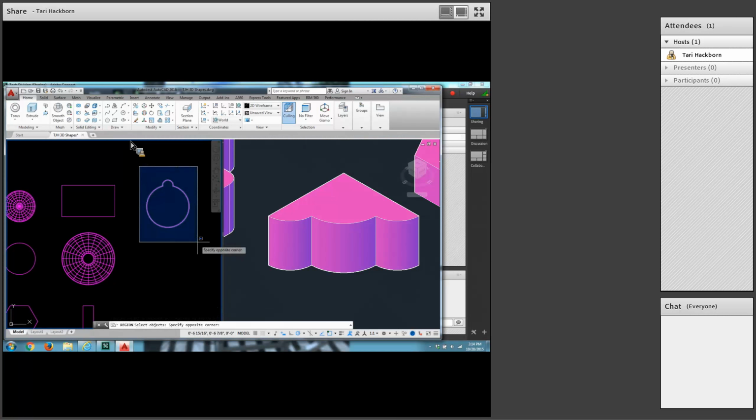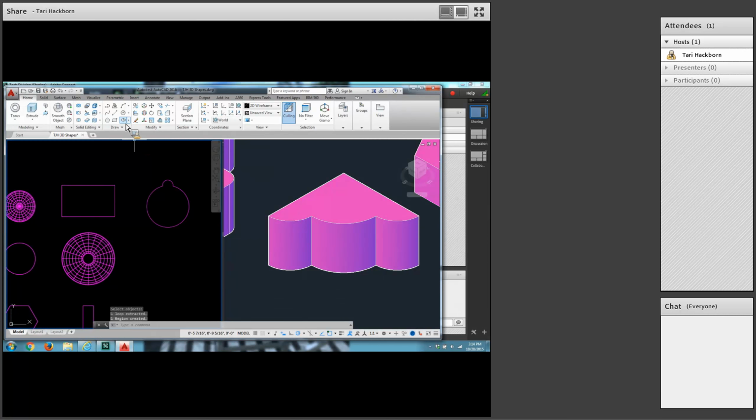Enter. By not making it into a polyline, you get to skip all those steps in the blue step 25. You can jump right to step 26, where it says to draw a line and to start it at 6, 6 3/4. Line 6, 6.75. Line starts right there, and pull it straight to the right and type 5/8 for the length. Enter to get out of there. That line is going to be what you revolve around.